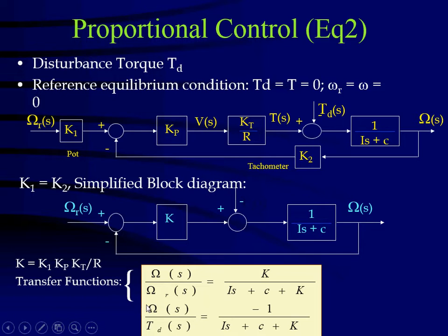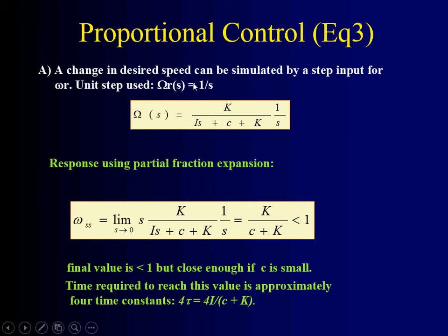Summary of proportional control, first order system. The output never reaches the desired value. Its resistance is present, and although the error can be made arbitrarily small by choosing the gain large enough, it is always with an error. So proportional control is very good, it's quick, but it leaves us with a steady state error.